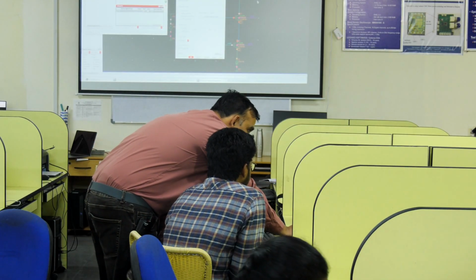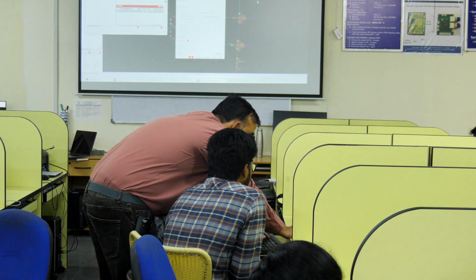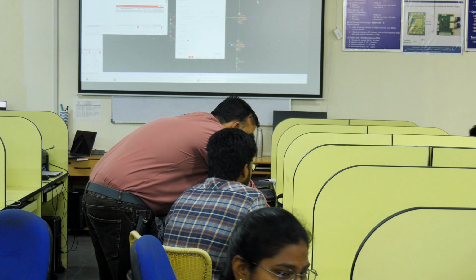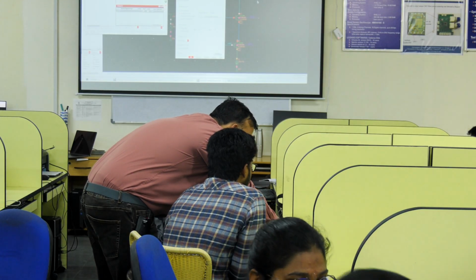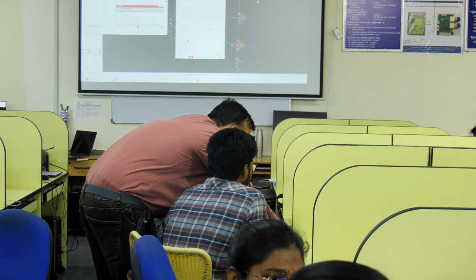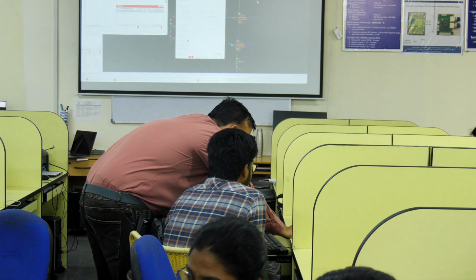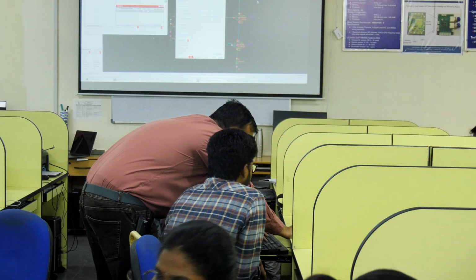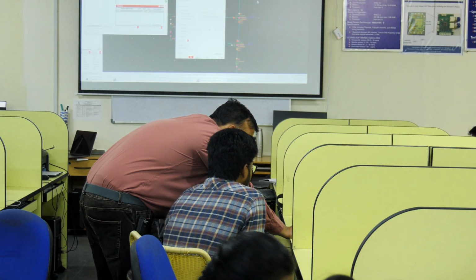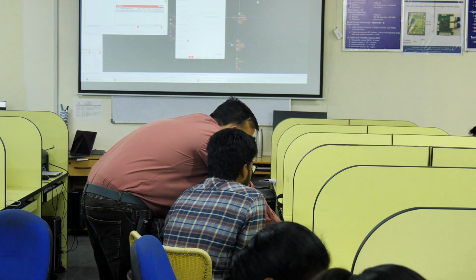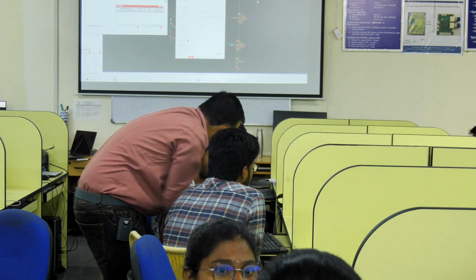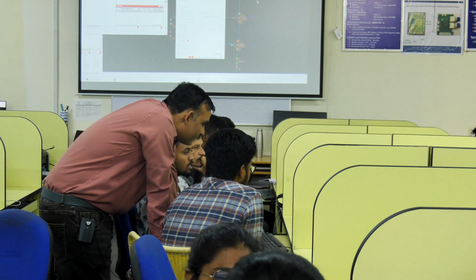So we don't connect. So what we do is now we can do edit in place. So now if I'm going to just edit this one here, and you wanted the VDD to be connected, right? Yes. VDD is in which metal? Metal 1. So let's just take metal 1, a path, and connect it till this point. So I edited one pixel, and automatically all of the pixels got edited. Now metal 1 gets connected. Connected. So that's it.